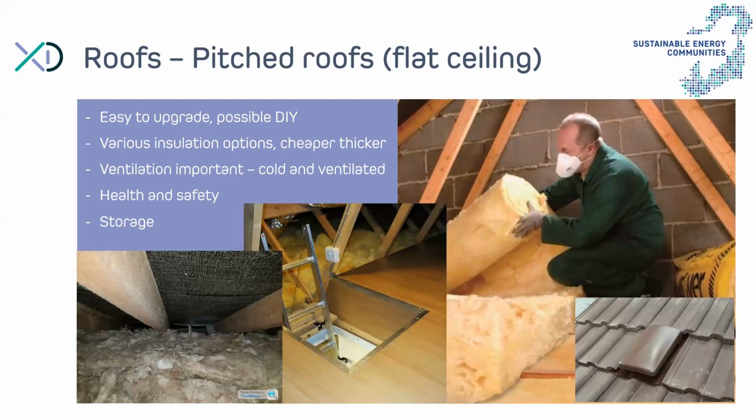So what we would recommend is to put over those downlighters either a big flower pot or a fire-graded cover. These are proprietary covers that will ensure there's enough air around the downlighter and that also block the airflow that would normally happen there around the downlighter. And then you can overlay the insulation over the downlighter without risk of overheating and potentially fire.